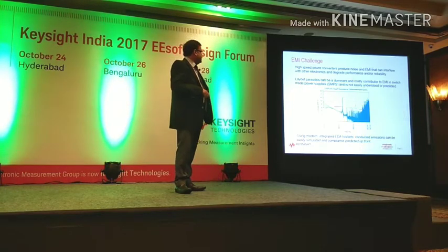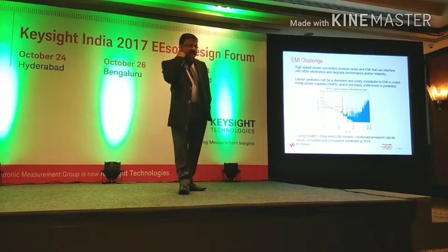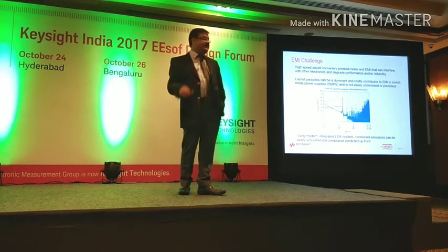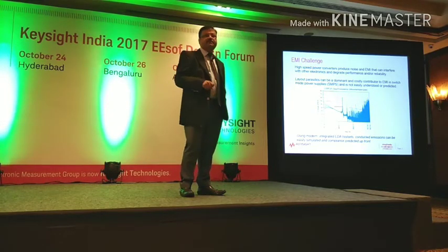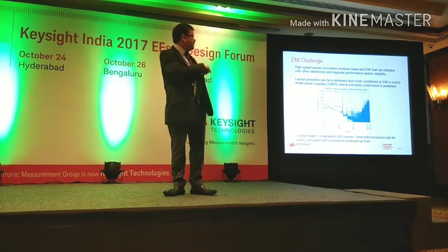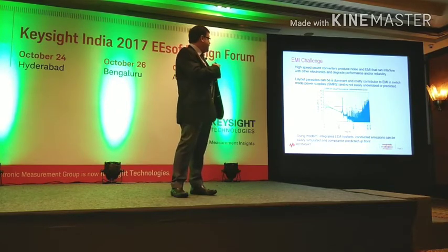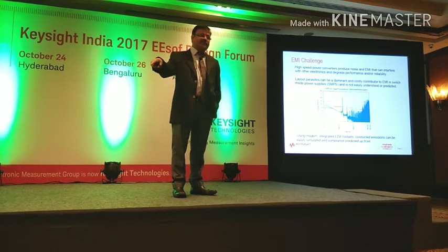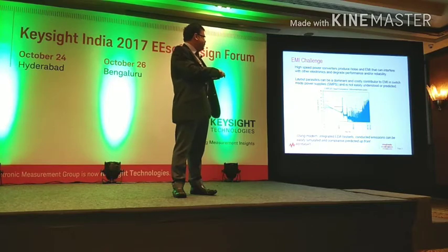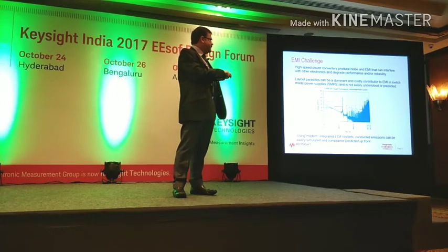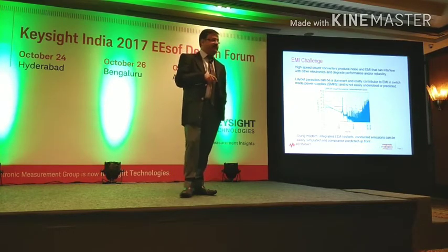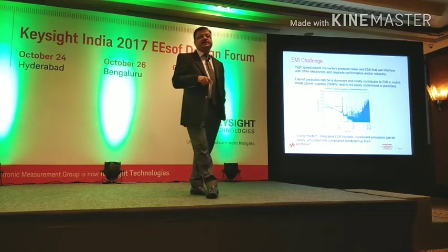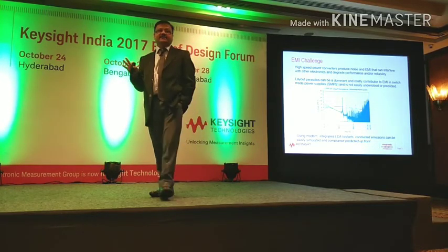Very quickly. One of the biggest challenges in DC-DC converters is to handle this EMI. The high-speed power converters are producing noise and EMI that can interfere with other electronics and degrade the performance, either your performance or the nearby electronics' performance. The layout parasitics can be a dominant effect and a costly contributor to EMI in the case of SMPS, switch mode power supply as you call it.